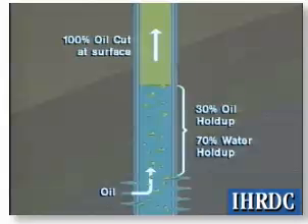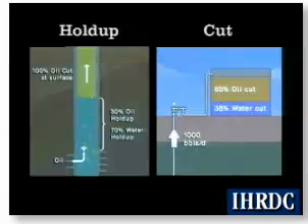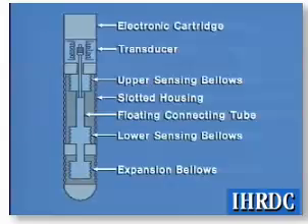Because of the density difference, water is likely to accumulate downhole in all wells, even when the water cut is small. The difference between the cut and holdup can be dramatic, especially at low rates. At 300 barrels per day (48 cubic meters per day), a 1% water cut at the surface may mean a 50% water holdup downhole. Measurement of phase holdup is done using a gradiometer, which measures the bulk density of the fluid over a 2-foot interval.